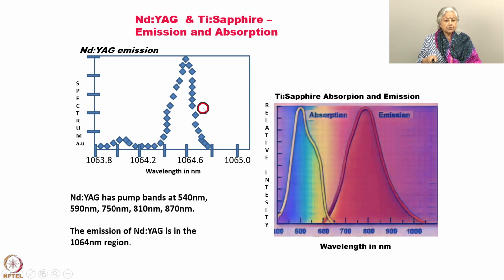Without going into the details, just believe me that in the case of Nd:glass, the bandwidth is larger as compared to Nd:YAG. So, they do have their own kinds of uses. YAG, with a smaller bandwidth, has its own use. Larger bandwidth can be used for obtaining very tiny, very narrow pulses, which we will be talking about.